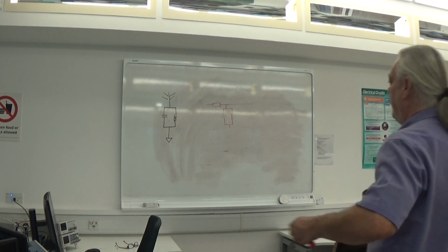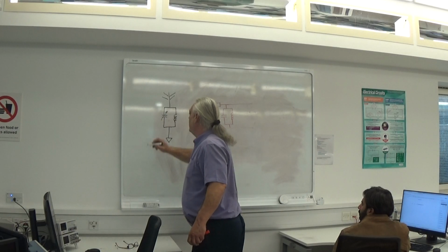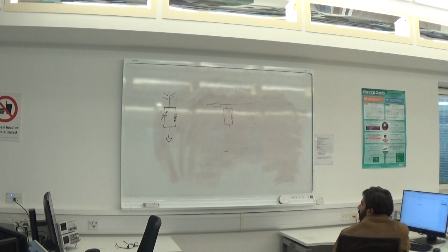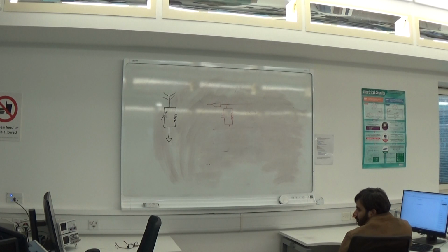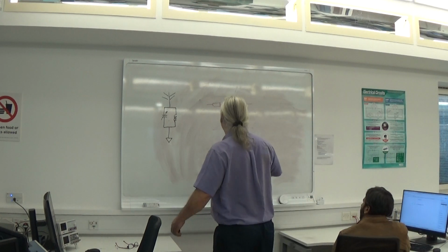So if I'm a bit cleverer, I can make the beginnings of a crystal set, so I make this a variable capacitor. Now I can tune into different stations. That's it. So if I can tune into different stations, what do you think that circuit does? So I can select one station from all of the stations that are out there. Bandpass, yes. So when you have that kind of configuration, you've got kind of a bandpass filter.